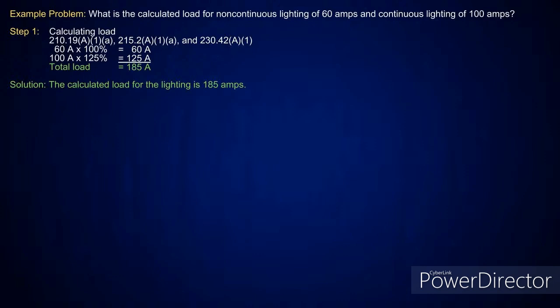So, question for you, that's in commercial, right? Or industrial. I think this is kind of interesting because I know in commercial there are 100% rated breakers. So, basically, is that load based on an 80% breaker? Well, this is because we're doing a service. Oh, I'm not doing a branch circuit. All I'm doing here is a full prep for a service calculation. I'm just telling you this is how you go about calculating.